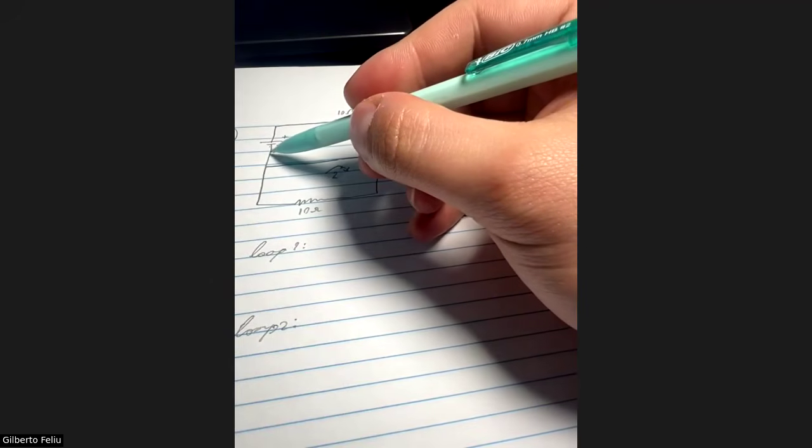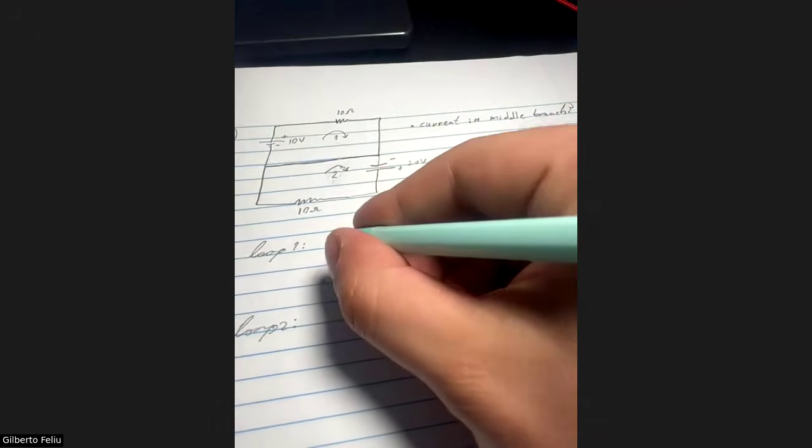All right, so we can start from here in the loop. We want to add up all of the voltages, and all of those voltages, as part of Kirchhoff's law, should equate to 0 when you add them all together. So, okay, you see this source right here? We're going clockwise. That's what we defined earlier. We are starting on the negative side of the battery, so that is how we will write down that voltage.